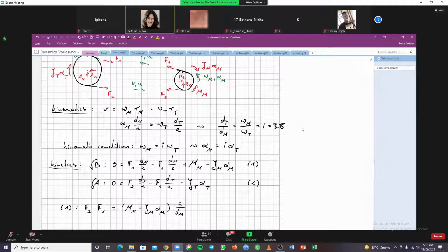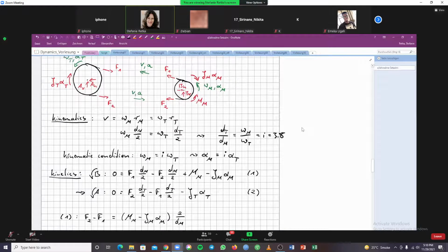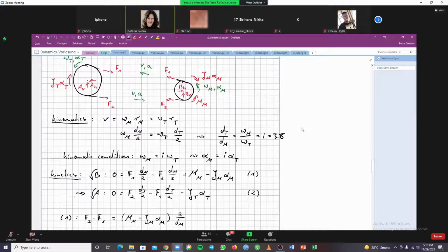Which moment about the drum? This is the equation of momentum about the drum, and there are only the tensions in the chain and the inertial moment. This one right here. There's no driving moment. The drum is driven due to the motor on the right and the chain that is connecting drum to motor. There's no additional moment. There's nothing else in our free body diagram.